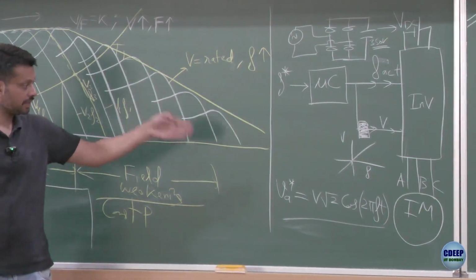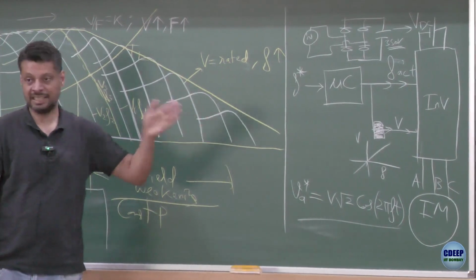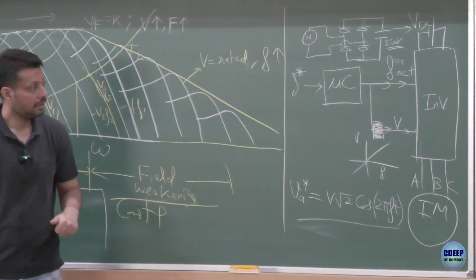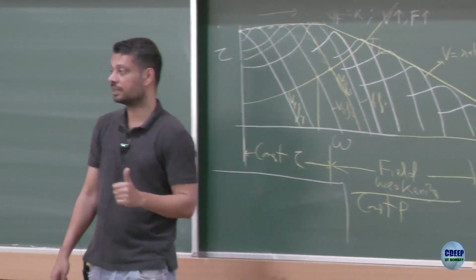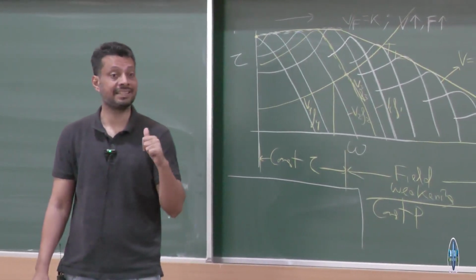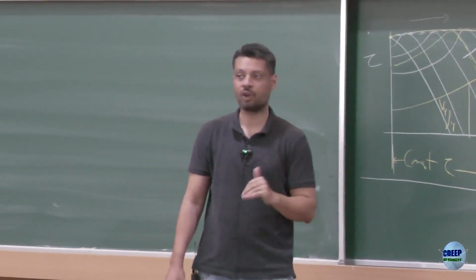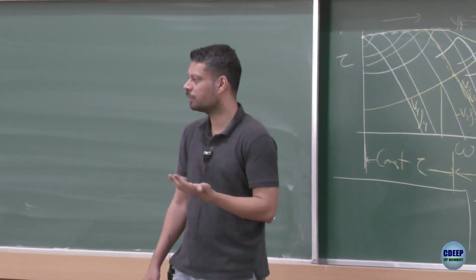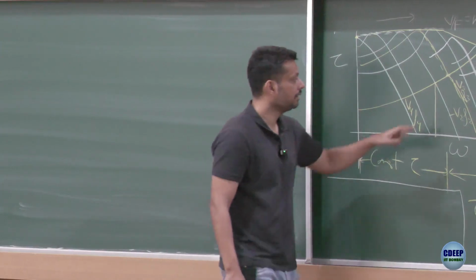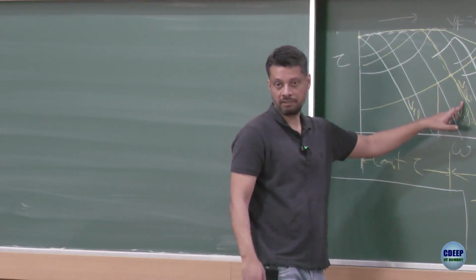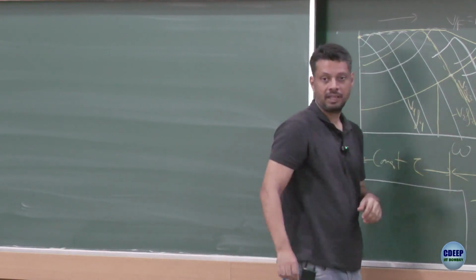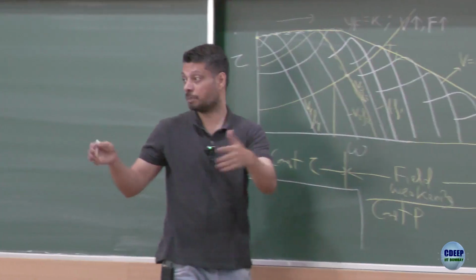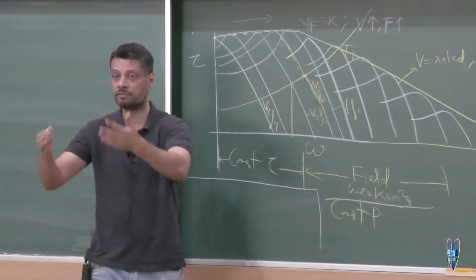What are the problems with this one? Yes, the initial current is low. Yes, you can get a high starting torque, but the first objective, which was that you want to run it at the desired speed, is still not completely met. Why? Because you are setting the frequency to be 50 hertz, let's say, or 45 hertz. Depending on the load, this is the point of intersection. If you turn on 2 more bulbs, and you remember the lab setup, right? You would turn on a few more loads,